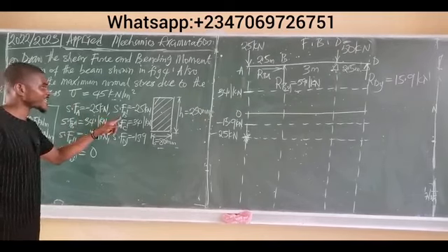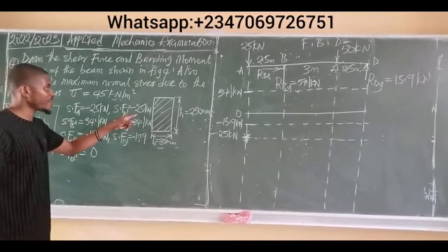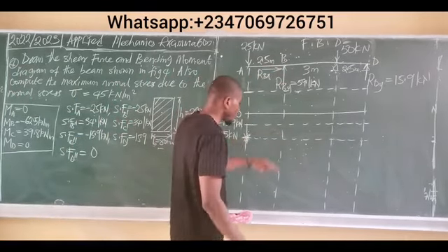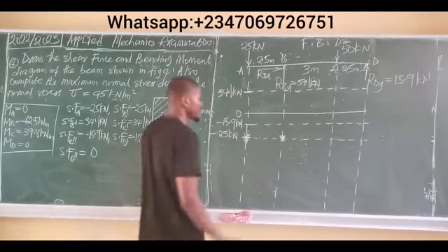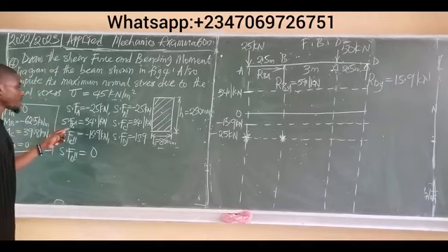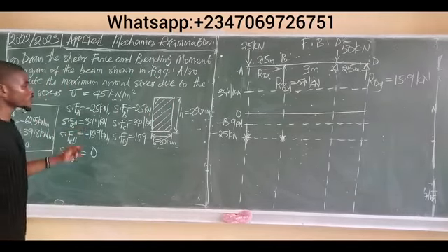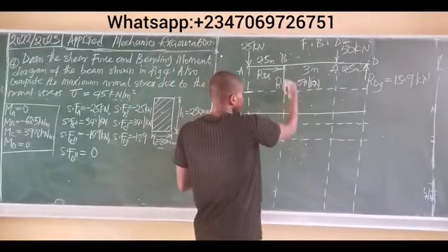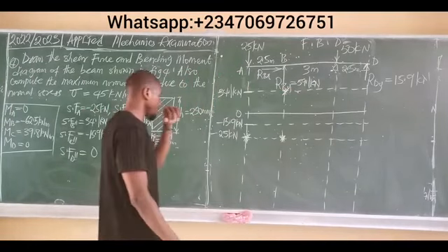Now, shear force at B prime, which means initially at point B, still remains minus 25 kilonewtons. And this is line B, so initially still remains minus 25. You simply asterisk that portion. Shear force at B double prime, which means finally at point B, the shear force became 34.1 kilonewtons. This is 34.1 kilonewtons. This is line B. See, this is where they meet. You simply asterisk that position.